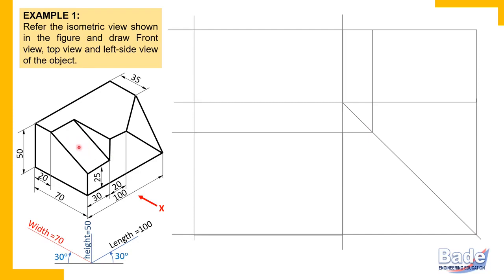Okay. Now, this surface is not a principal surface. It has a principal edge, and one more principal edge, but these are parallel principal edges. This is a non-principal edge. So this surface does not have two principal edges which are perpendicular to each other. Same way, this is not a principal surface. This triangular surface is not a principal surface because it doesn't have two perpendicular principal edges. All three edges of this triangular surface are non-principal edges.